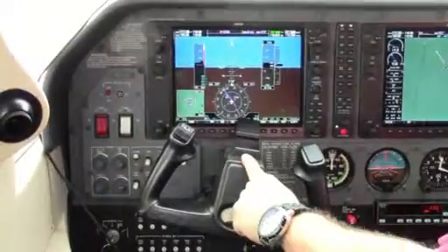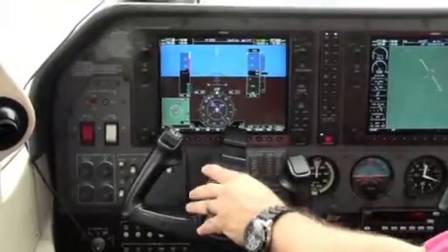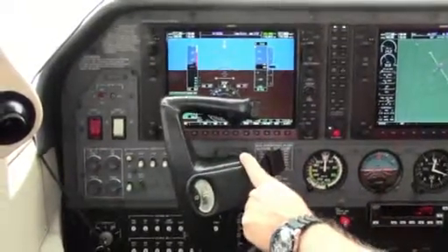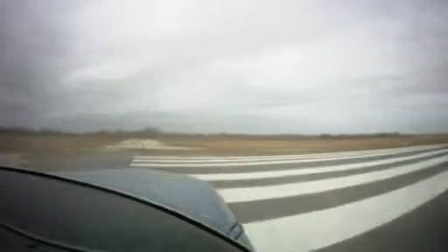It's always preferable to take off directly into the wind when this is possible. However, sometimes the circumstances will indicate otherwise. So the pilot must be familiar with the techniques that involve a crosswind takeoff. The technique used during a crosswind takeoff is almost the same used in a normal takeoff, except that the aileron control must be held into the crosswind. This will allow the aileron on the upwind to be raised, imposing a downward force on the wing to counteract the lifting force of the crosswind, preventing the wing from rising.